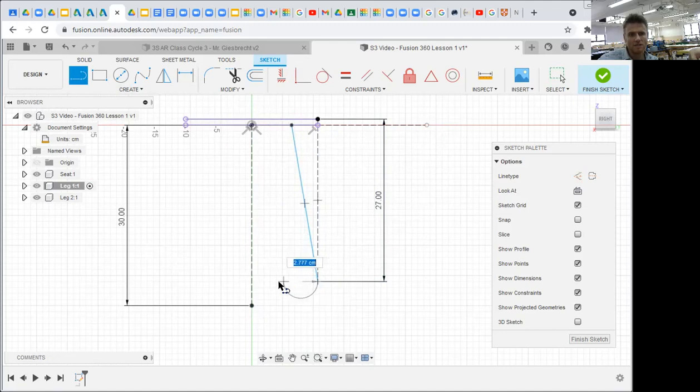Now, if I hold down my mouse button, you'll notice here that I've created a curved line. Some of my students have worked on this in the past, and they say, my line won't go straight. It's because you're holding down the mouse button. So just push escape and then do that again. And this time when you do it, you just need to make sure that you don't hold the click button when you're doing it, because that's what's going to happen, okay?